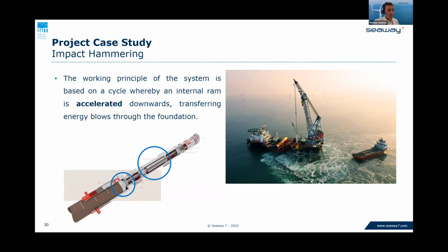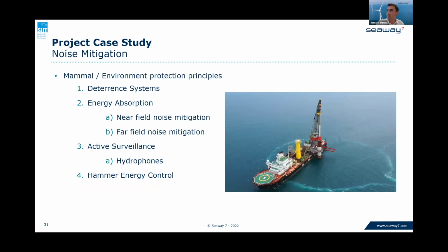This technology can be used standalone, so you don't necessarily need vibratory driving, but what we're looking at is using vibratory driving due to the efficiencies and not requiring other tools, and also the speed at which hammering occurs is swifter. And also with impact hammering, although it is the traditional sort of technology, there are some challenges that come with it. One being noise, and that's where noise mitigation systems come in.